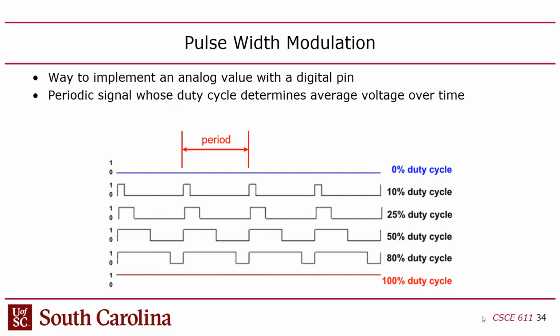So if you're using an LED, for instance, to dim an LED, if your frequency is too low, you'll actually see the LED flickering. Like you'll see it turn on and off, right? But you don't want to see it turn on and off. What you want is for it to appear to be dim or bright. You shouldn't be able to perceive the LED turning on and off, as a human looking at it, right?